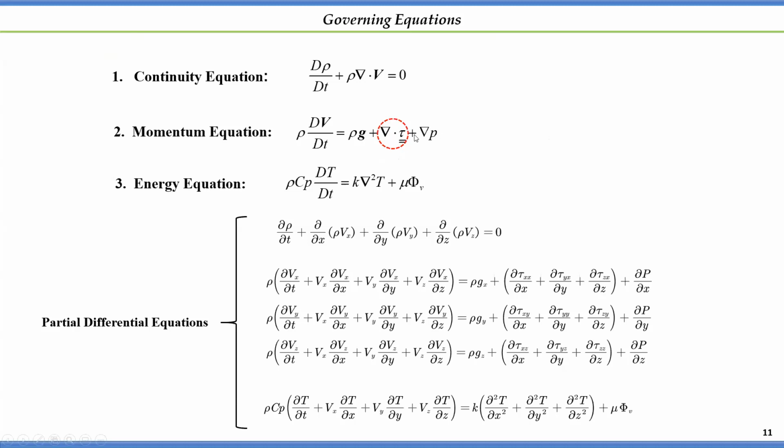When you plug your constitutive equation in here, you see the application of the momentum, continuity, and energy equations to a very specific kind of fluid. When you consider this term for a Newtonian fluid, then this equation is called the Navier-Stokes equation. Here we are calling it the Cauchy momentum equation because it is in terms of the stress tensor.